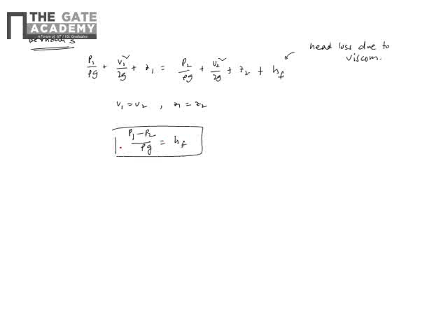As we have seen from the previous analysis, the pressure should decrease, so ∂p/∂x is negative, to balance the shear, to balance the fluid friction. That is almost clear from the force balance. This is one equation which we will use later, but now let's again take τ as minus ∂p/∂x into r/2. So this was the first equation.